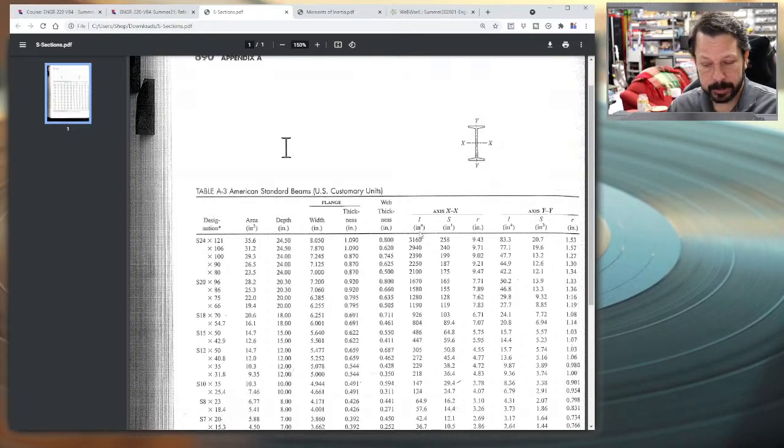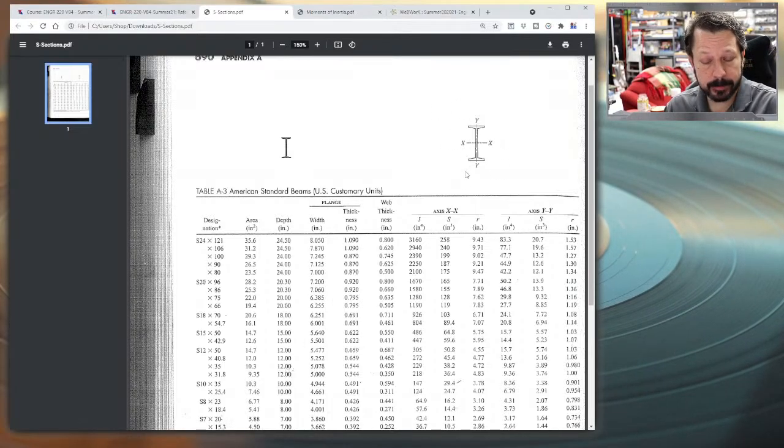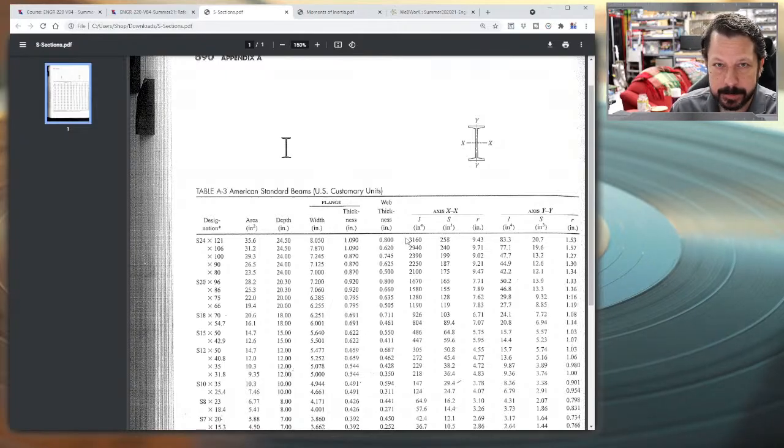So remember, it's in the denominator of our stress equation. It's also going to be in the denominator of deflection equations when we calculate the amount of bending that occurs, like the number of inches of bending or millimeters or whatever. It's going to be in the denominator of those equations also. And notice when you're talking about loads that are perpendicular to XX, which is the normal orientation, you get really large values of moment of inertia compared to those for the same beam but loaded on its side. And so a lot of beams, not every beam will be that way. Some beams are symmetric, they would be the same either way. But I-beams and T-beams and C-beams are going to have one direction that's much stronger than the other as far as bending and flexural stress go.